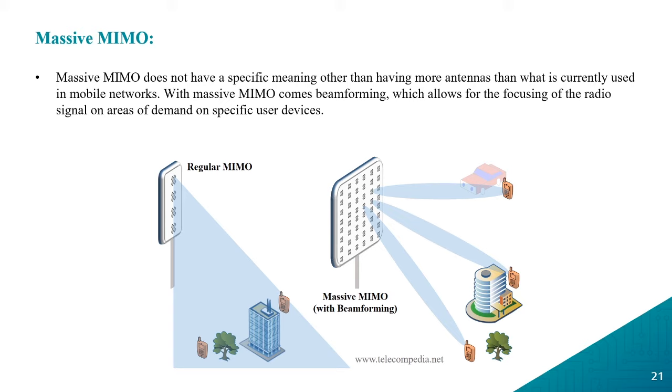Beamforming refers to the function of smart antennas which control the properties of the electromagnetic wave radiation pattern of an array antenna by aligning the amplitude and phase of transmitting or receiving signal in array antenna elements, thus increasing the array antenna gain in the intended angle of direction and at the same time suppressing gain in other angular directions where interference signals would result.